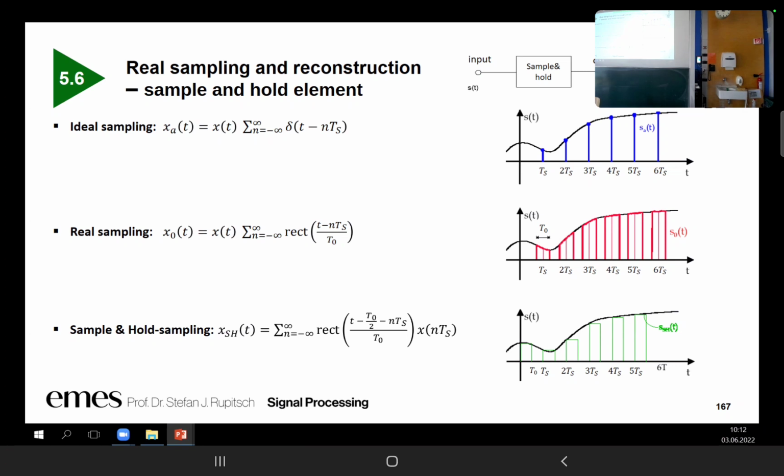But this is impossible from the electronic point of view. You only pick out one signal and then go back to zero. You always need a certain hold period to be able to convert it from the analog world to the digital world. But we are trying to reduce this whole physics. In case of the sampling, it's not required because we take this value and then it remains constant. If you take a look here, we take this value, that remains constant. Take this value, it remains constant, and so on.